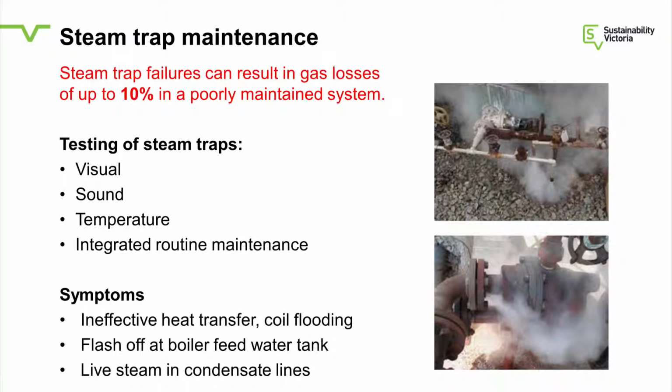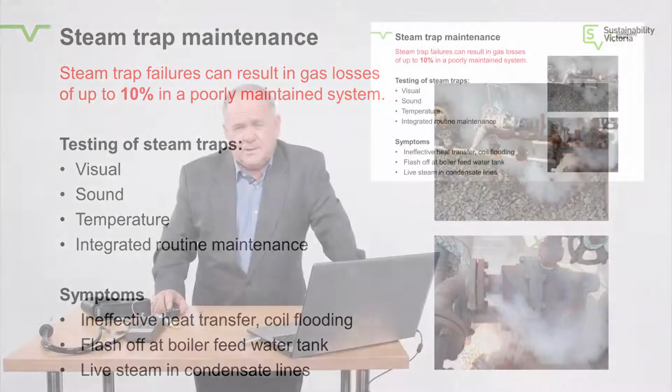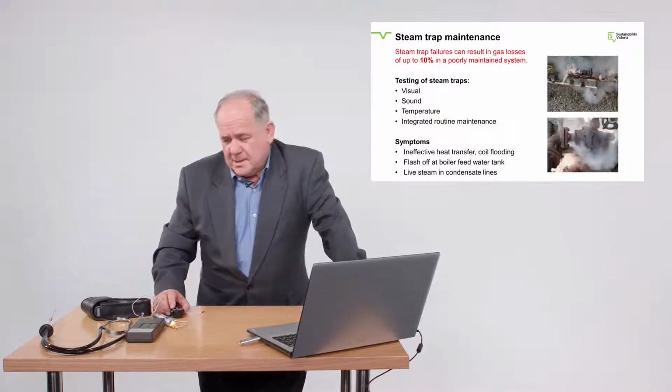Now, how do you test? I guess you can use steam trap companies to do the surveys initially, but it can be quite costly. So you've got the choice. You can either do that every year, or you can train your own maintenance people to do these things. Once you've established where all your steam traps are and types are, it's not that hard to incorporate it into your regular maintenance schedule.